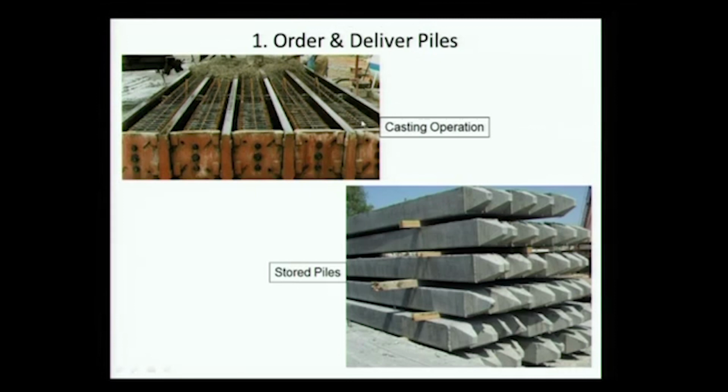So you can see here, if you have not visited a precast yard, it is something which you should do as a part of an industrial visit. You will have molds like this into which concrete is poured, and then it is stripped, cured, and you will have piles ready for delivery in this form. If you place the orders, these are standard length, standard dimension, and I can base the number of piles in my foundation design on that. If you can't order piles in your area, you might have to set up a precast yard on your site which does something like this.